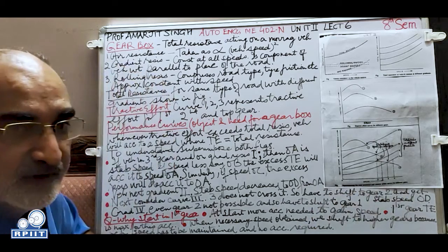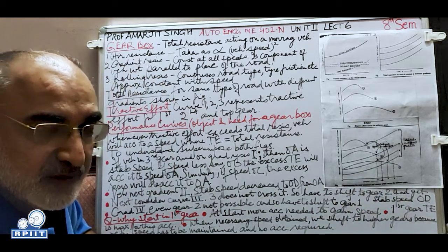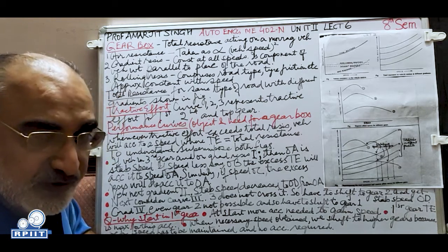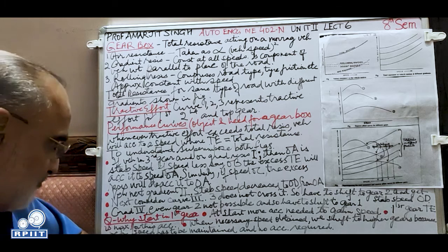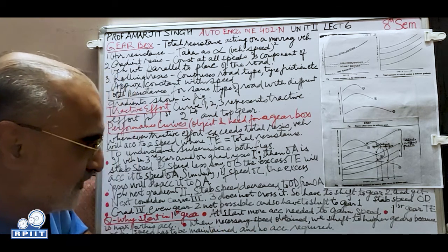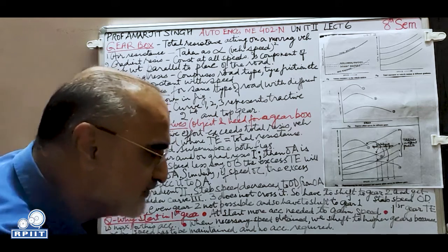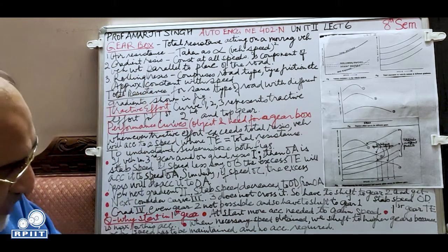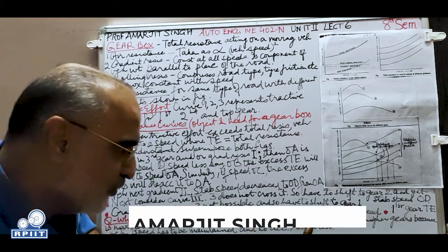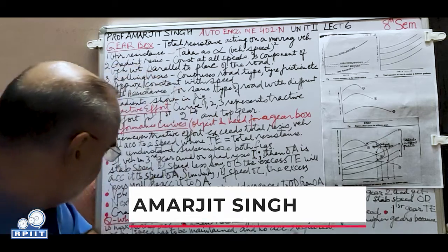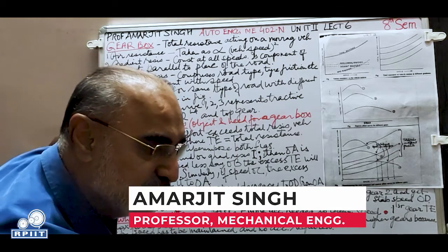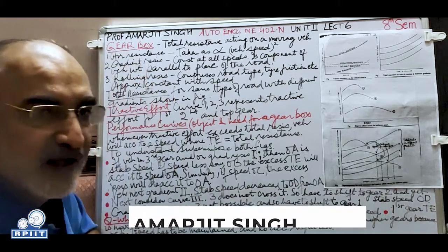How is this? When we study the inside of the gearbox, the number of teeth, driven shaft, driving shaft, you will come to know. When necessary speed is obtained, we shift to higher gears. You have obtained the speed from 1. Now we can shift to 2. We shift to higher gear because vehicle speed has to be maintained and no acceleration is required. From 2, as the speed increases, you will go to 3.